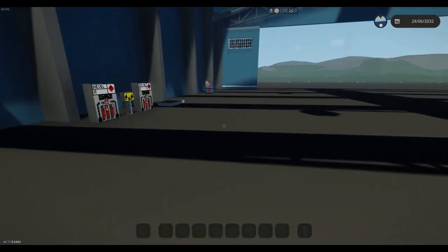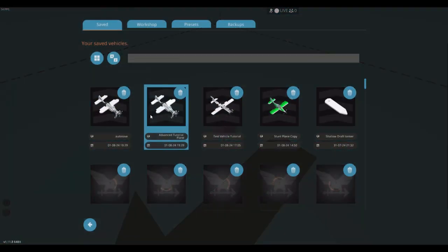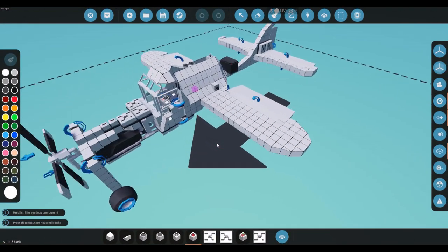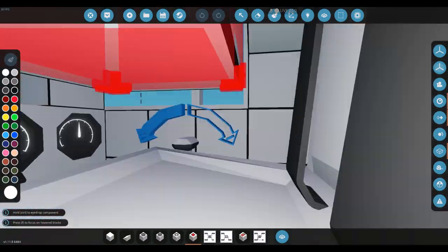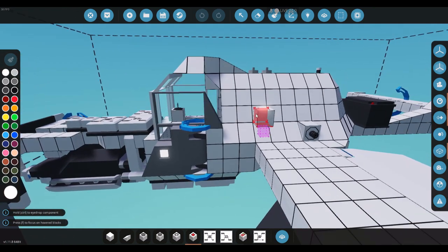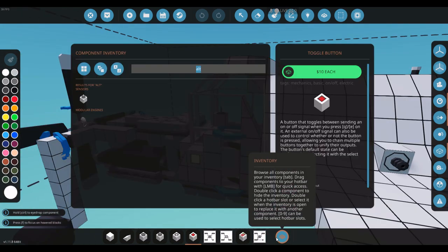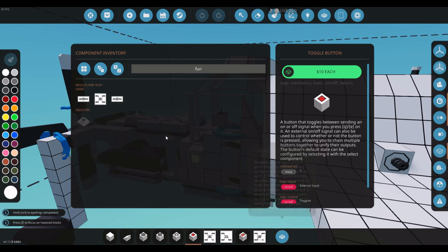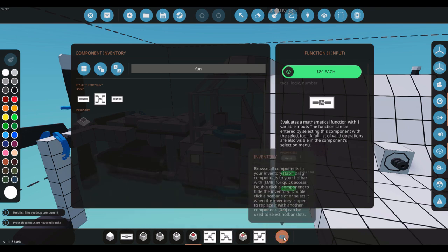So something you could do to mitigate that. By the way, within 5 values is still quite good. If you want, you could totally have that be acceptable, and you just know when you use your altitude hold, it only goes within about 5. But right now, for the fixes, let's say you did want to do something more accurate, you would grab what's called a function block. We'll put that here.